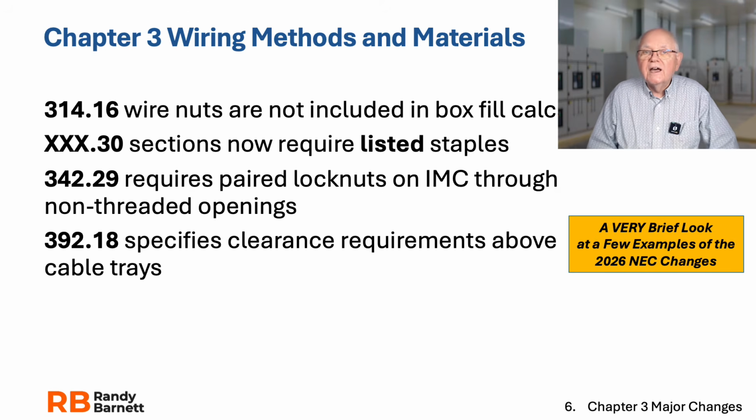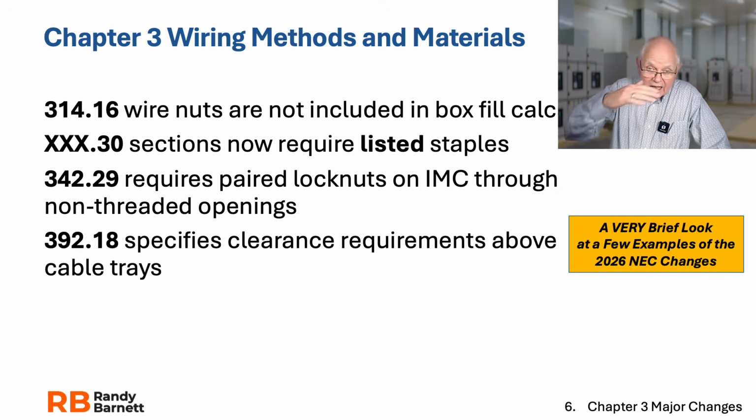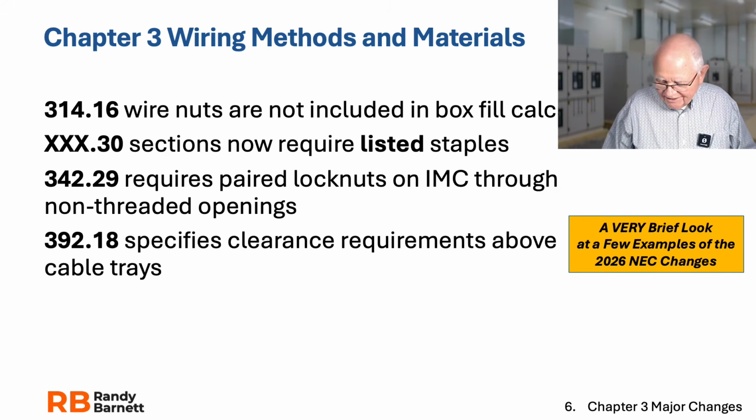392.18 now specifies some height clearance requirements above the cable trays. So that can be a pretty important one, as you know, especially if you had to ever work in a cable tray after installation. So take a look at 392.18.